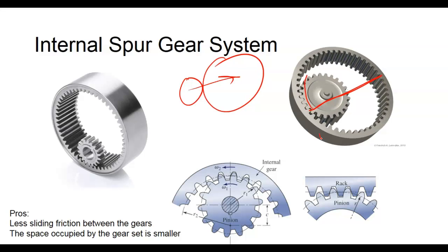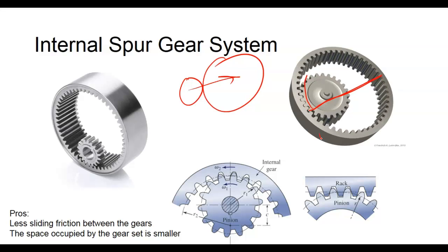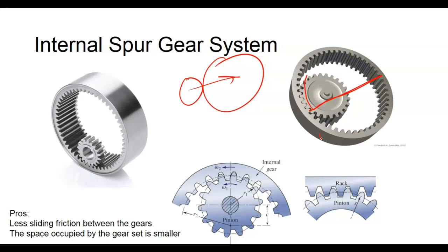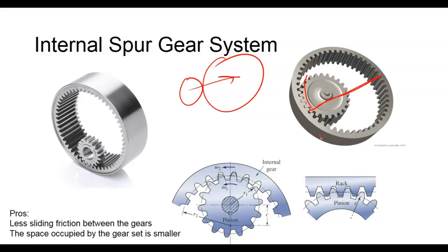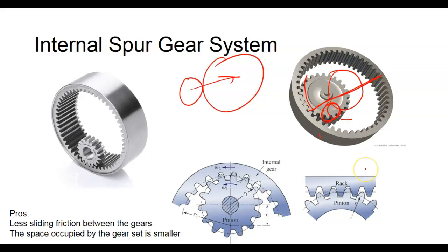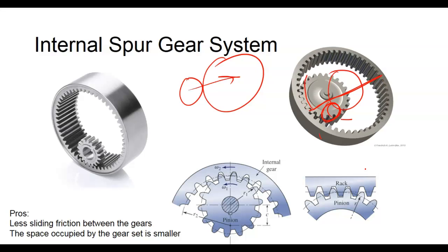First time I saw this was on a. So is there normally another gear inside the circle? Could be. It depends on where you put an idler gear in there, but we know what idler gears do, right? There's a video up there, but you're right. We come over here, we can do this, and then we can put a gear right there. Well, this would be considered an idler. It would not have anything to do with the torque or the speed, right?